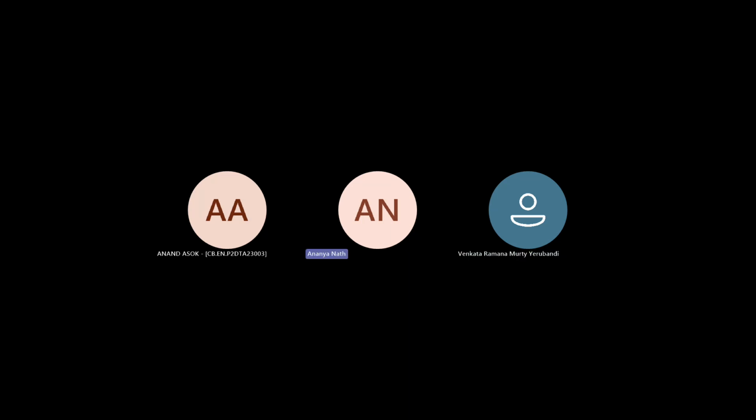If you're making the CAD files, then you can convert them to 3DMF also. There is a new file format for additive manufacturing called 3MF or 3DMF. That is a recent development, and it is compatible with most of the software. I don't know if you are going for FDM; I think for Cura it is easily accessible. But in other systems, we are still using STL only.